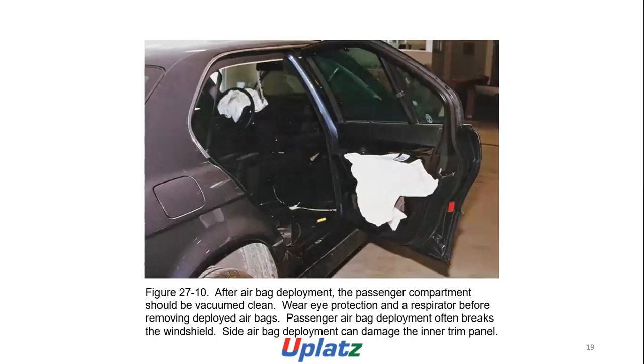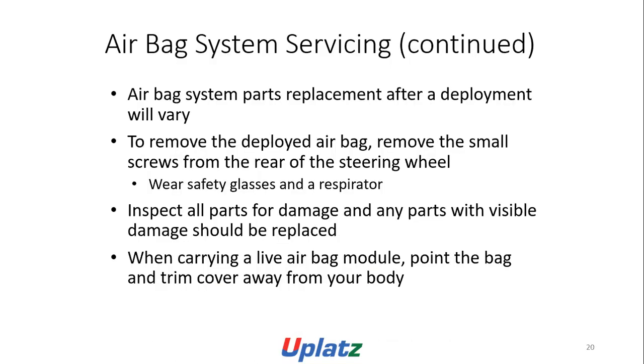The figure shows that after airbag deployment, the passenger compartment should be vacuum cleaned. Wear eye protection and a respirator before removing the deployed airbags. Passenger airbag deployment often breaks the windshield. Side airbag deployment can damage the inner trim panel.